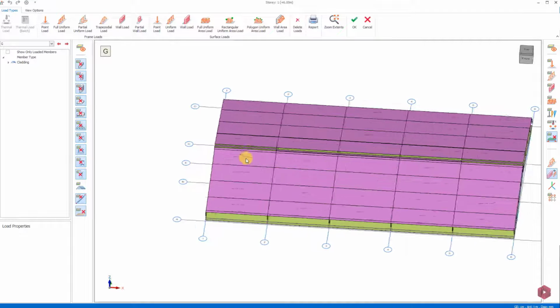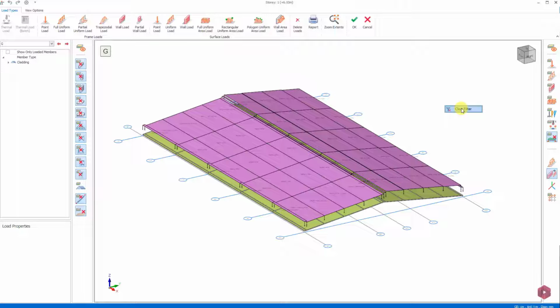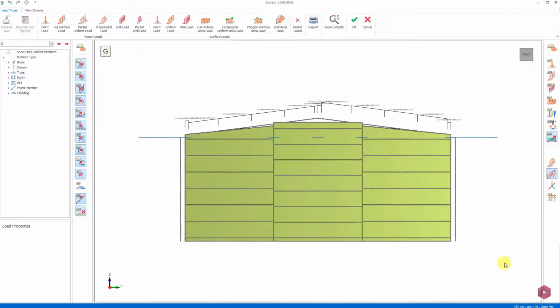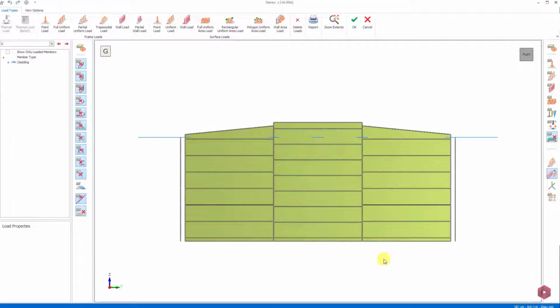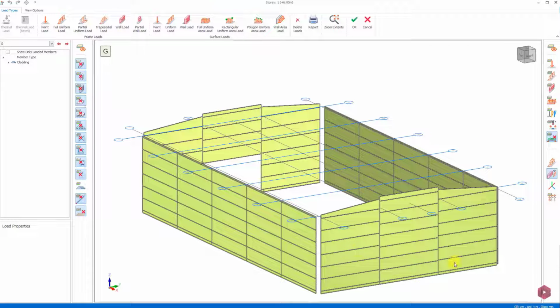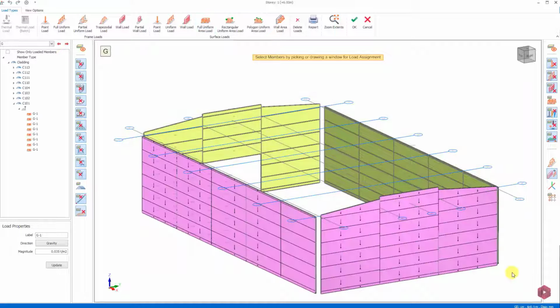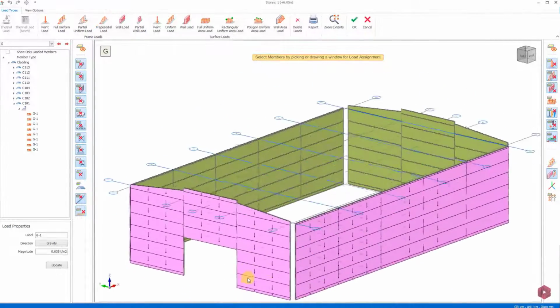Then, let's get the right side view, select all facade panels and mark Filter from the right-click menu. Thus, the facade panels are selected as a group. Let's select the Area Load command and assign the 0.035 load for the area load by selecting all facade cladding. Thus we collectively defined the cladding weights of all facade objects. We can view it again with all facade panels with the Clear Filters option from the right-click menu.